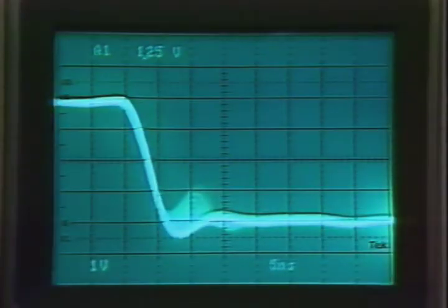When a single electron from the scanning beam enters a tube, it causes several thousand electrons to leave. This process is self-limiting in that only so many electrons can be drawn from each tube per second. But this number is very great, and the limiting or saturation tends to even out the light from the waveforms. One trace is easily visible, but 1,000,000 traces are only 100 times brighter, not 1,000,000 times brighter. This saturation effect helps us see single sweep events, even in the midst of millions of similar events.